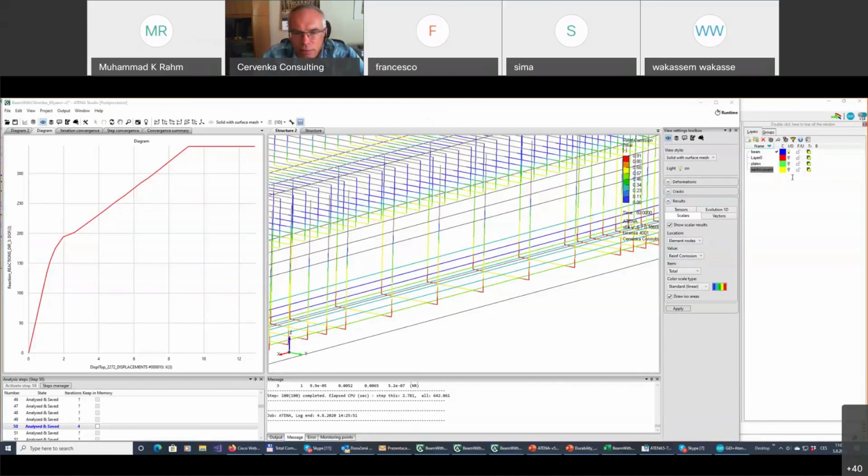The approach we are considering is based on the fact that for engineers, it's not so important that we lost some concrete. What is more important is the fact that once spalling starts, the corrosion rate changes. Because we know the distance of the reinforcement from the surface, using the current empirical models available in the literature, we can estimate when the cracking starts, when the spalling starts, and based on that, we can increase or change the rate of corrosion.